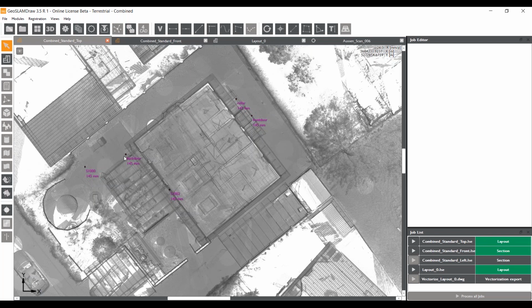But then you are only looking at one small part of the point cloud and not at the point cloud as a whole. If you try to compare the point cloud as a whole using a point-to-point algorithm, you have other issues, because the distribution of the points is not completely at the same space in 3D space. So I dislike comparing point clouds to each other.